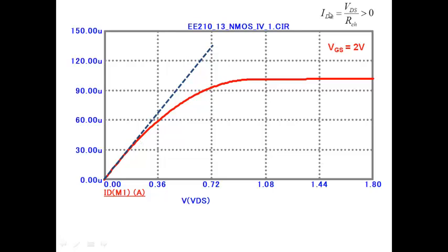But as you make VDS larger and larger, the current no longer increases linearly because the change in R channel also becomes significant. So R channel also starts going up, and therefore it starts bending here, denoting the fact that R channel is increasing. So it no longer increases linearly like this, it starts bending there. Okay, because the R channel is also increasing. And as you keep on increasing VDS, R channel keeps on increasing here. Eventually, you reach a stage where you can see that my current has actually become constant. We'll see why it becomes constant in a minute.